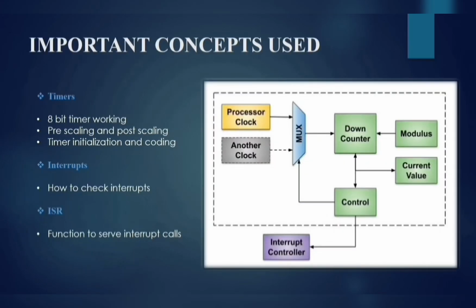Further, we discuss the important concepts used in the project. Here we use an 8-bit timer, which is a timer that counts from 0 to 255. When it overflows after 255, that generates an interrupt which can be polled.